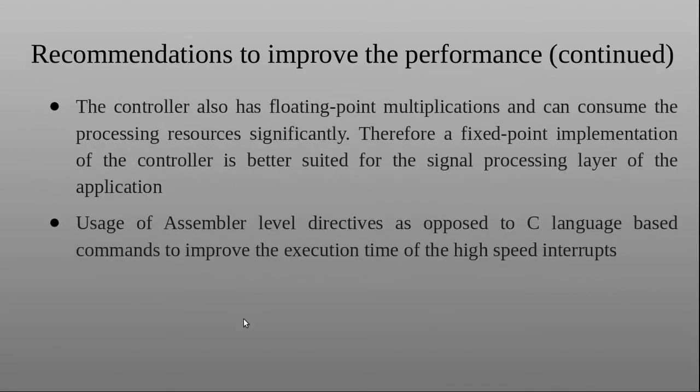Coming to the continuation of the recommendations, the controller also has floating point multiplications and can consume processor resources significantly. Therefore, a fixed point implementation of the controller is better suited for the signal processing layer of the application. However, fixed point processing is a little complicated and has to be carefully designed.